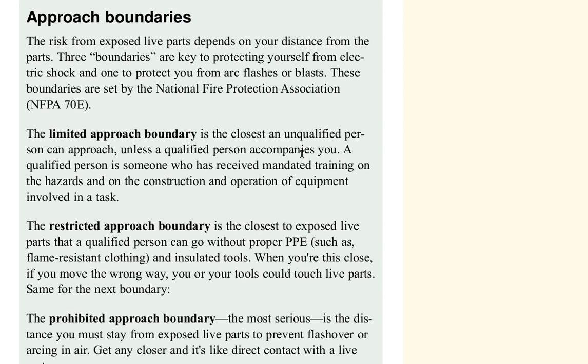The restricted approach boundary is the closest to exposed live parts that a qualified person can go without proper PPE, such as flame-resistant clothing and insulated tools.